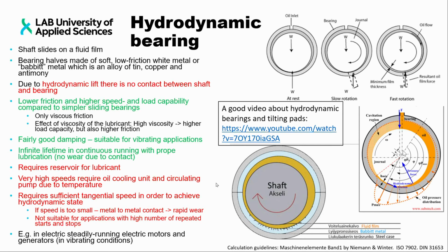And if the shaft is deflecting, that will sometimes cause friction and wear at a certain point. So this area between the shaft and the bearing should be as cylindrical as possible. And there's a solution to that which corrects this sort of anomaly, and that is tilting pads.